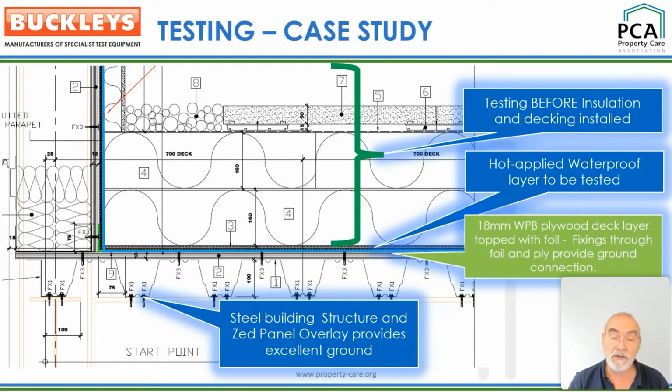I think it's also worth considering in a remedial situation where the building has been in use for some time, that if flaws leading to leaks have occurred, the water will have entered the building through the structure of the roof space and will have infiltrated, possibly tracking several metres before becoming evident within the living space. In these circumstances, electronic leak detection is extremely useful in locating the sources of the water leak, as the water itself acts as a conduit for current in both wet and dry systems, and both would typically be able to detect the source of the external flaw that allowed the water to enter.